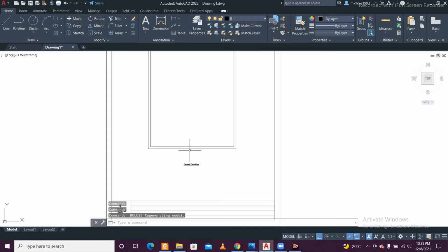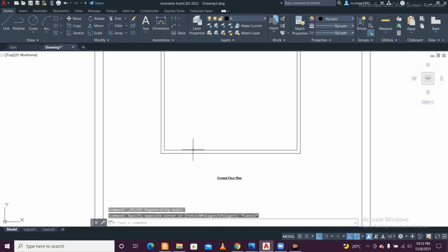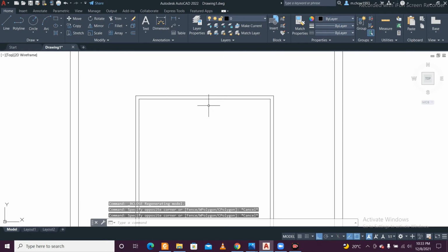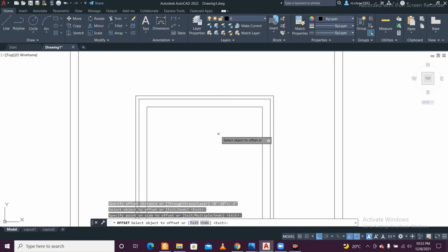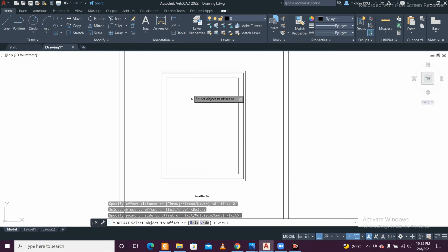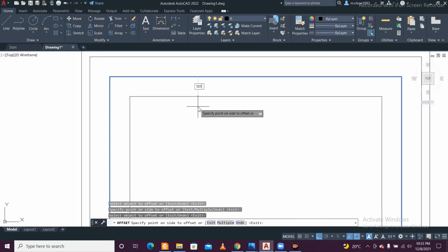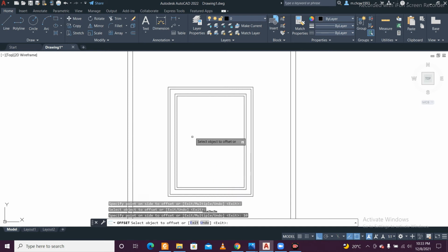So this is our suppose boundary wall, and now we'll just plan our building here, and suppose we'll leave an offset of 2 feet from all sides. This is the boundary wall, offset of 2 feet from all sides. Now this is the area of our building, and in this building area we'll leave an offset of 10 inch. We'll be considering 10 inch walls. In some places there are 7 inch walls, there are 9 inch walls, so you can consider accordingly. With plaster I'm considering 10 inch walls.